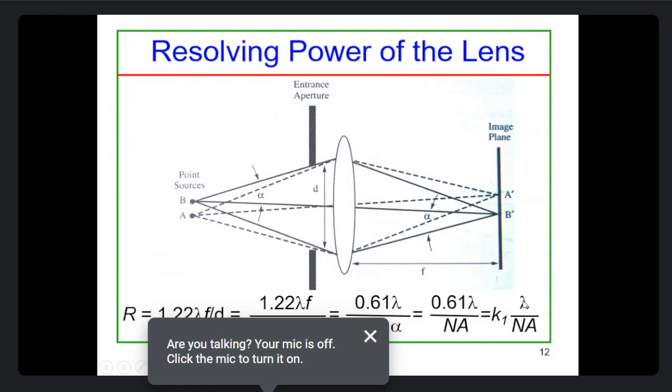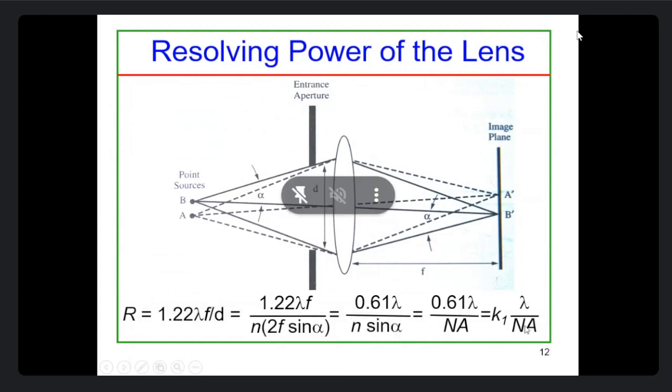And if you can judiciously combine these two factors together, a little bit on lambda, a little bit on NA, without burdening one particular factor, because you have two factors to play with, reducing one thing, increasing another. So a little bit of reduction in lambda, a little bit of increase in this. By a judicious combination you can do that. That's a smart approach people follow. All these are possible solutions. And as I mentioned, people have already done much research, and research is still going on, particularly in this aspect.